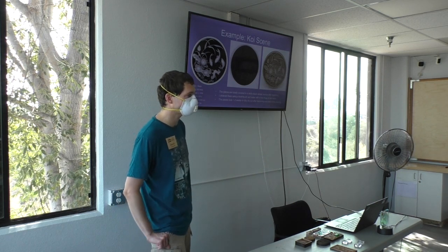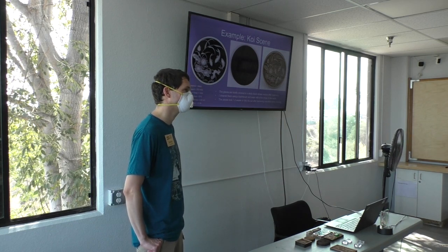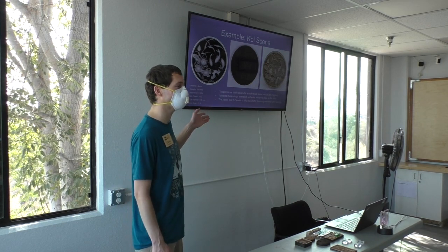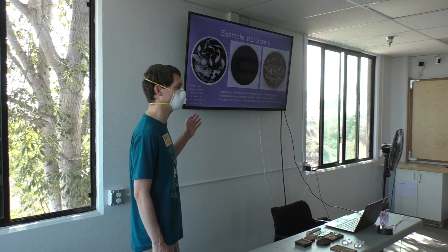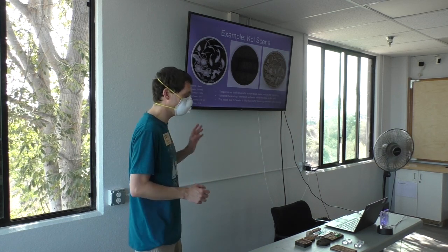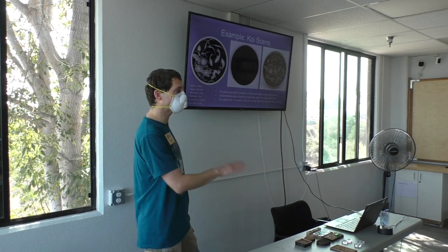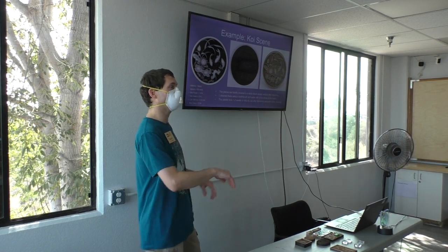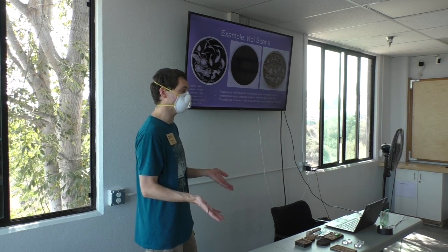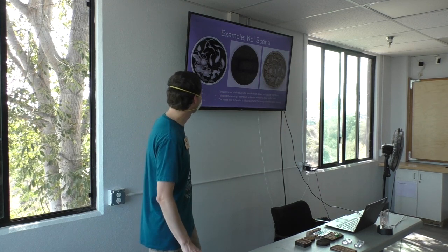But if you used a high grit, you could at least remove some of that raised grain. It might work. The grain raising isn't noticeable at all in the engraved areas because they're so rough. It's all texture. It's really just the surface around the engraving, which although it has the grain raised, isn't an issue because that can be sanded. As long as it's not the engraved part, you can go to town. Right. So that's.